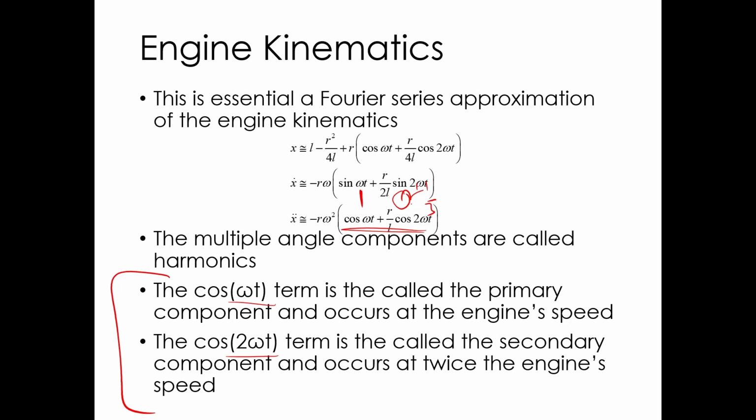Secondary gets to be an issue. So for engines like some V10s, V10s might have secondary imbalance problems. They're very common in V10s. I can't remember if it's all V10s. There's different kinds of V10s, split pin and shared pin, but I know in a lot of V10s the secondary imbalance is a big problem.